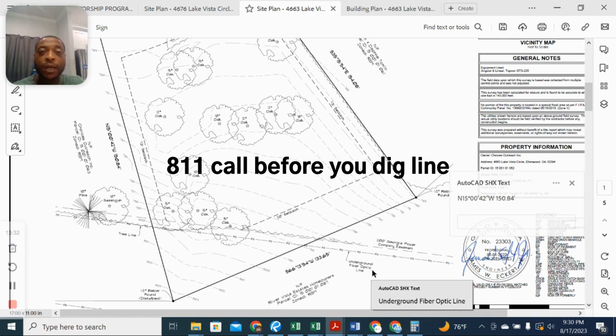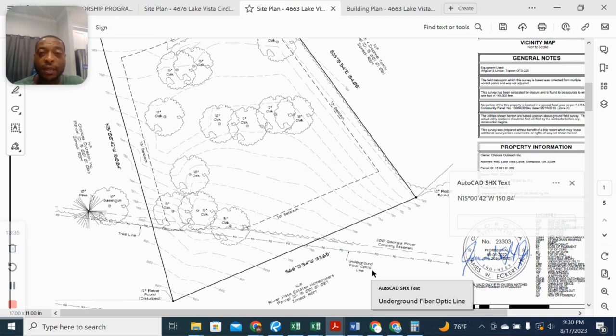If you dig somewhere and you hit something that you shouldn't hit, like some cable, some gas line, some electrical line, the fines are hefty. Ask me how I know. All right, so you don't want to do that, and also it's being a responsible builder. So knowing this, that also made us aware to be able to call these things in and verify all this stuff. So when you call 811, they will come out and they will do all that verification for you.